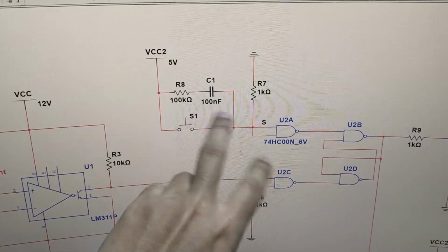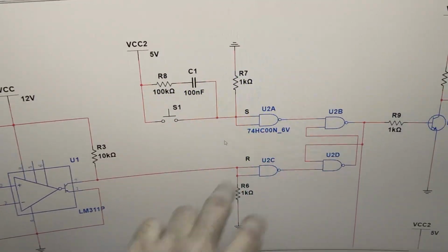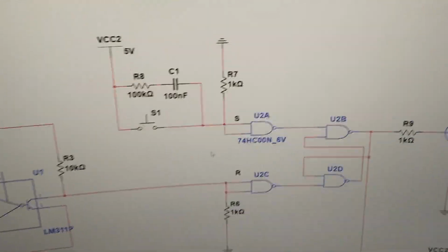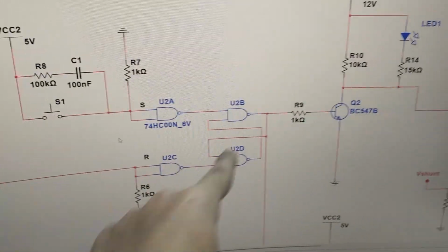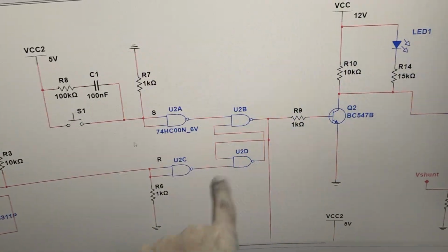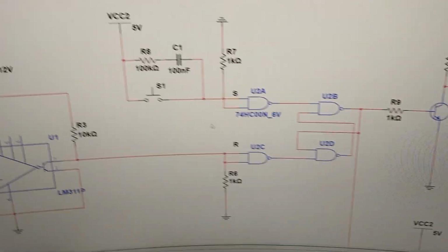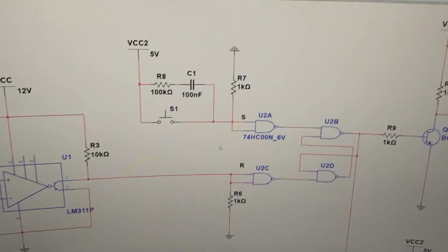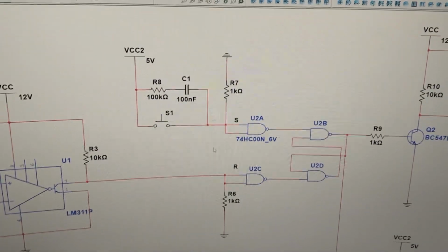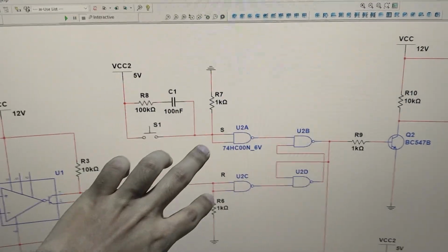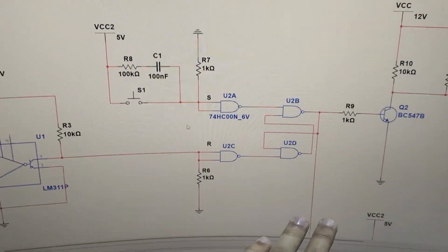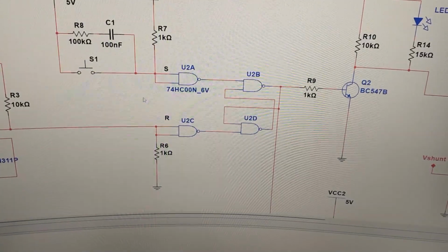And you can see here there's one series RC, and that's because this is a sequential circuit, because the feedback is there between input and output, as a latch always has. We always say that Qn+1, if both inputs are 0 0, the output would remain no change, right? But for that we need to have a previous state.